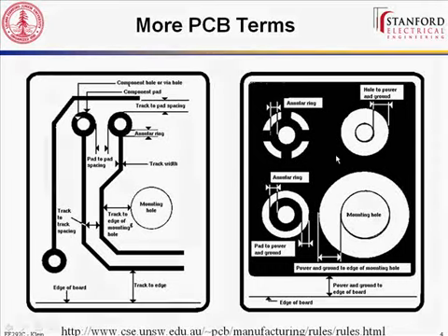So what's the point of having an entire layer that's just one signal? This is most useful for your power and ground. You're going to need to have, for example, VCC, which for your project will be 3.3 volts. And you're going to need to have ground going to a whole lot of different places on your board. And it's the same signal going everywhere. By having an entire plane layer, first off, it's very easy to route to, because just about anywhere you are, you can just drop a via to this layer and you magically have ground, and you don't have to route a connection.